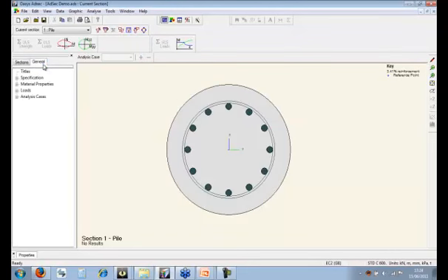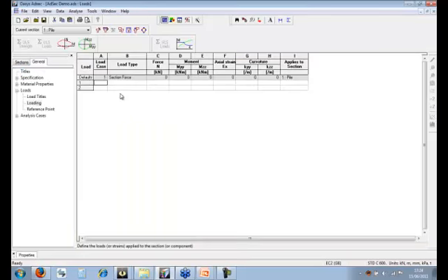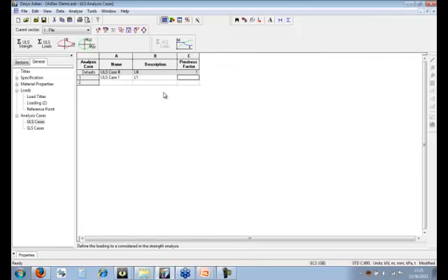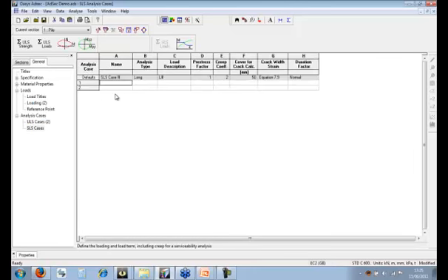How do you go about analyzing it? Well, first put your loads in. So, let's see. So this will give me my ultimate load. So say 1500 load, and in the analysis case, you've just got to put your analysis case in. So your ULS case is your unfactored loads, and your SLS case is a factoring of that load, so 0.75 of the load.